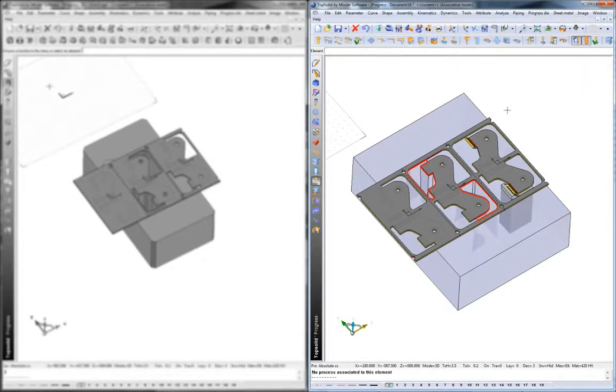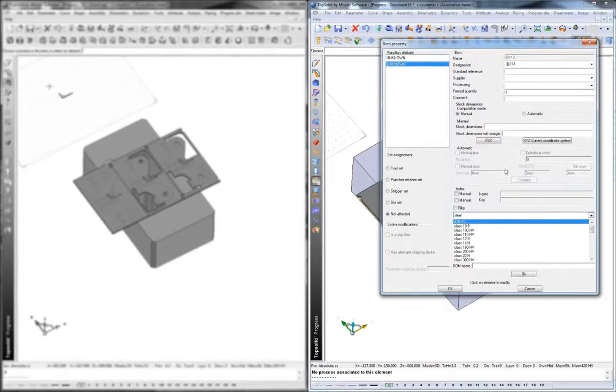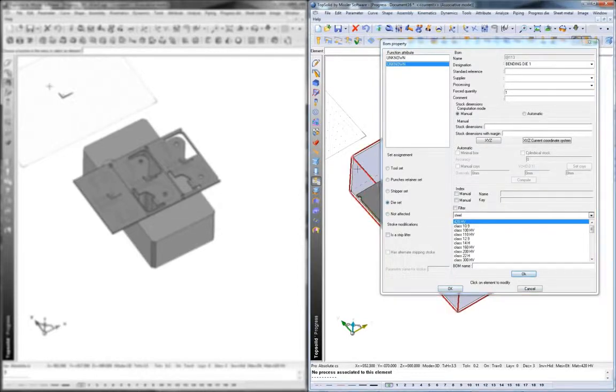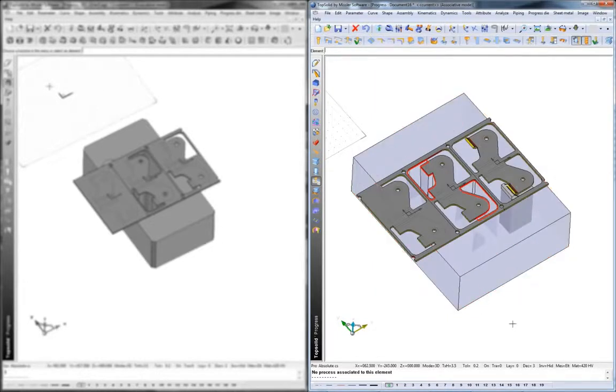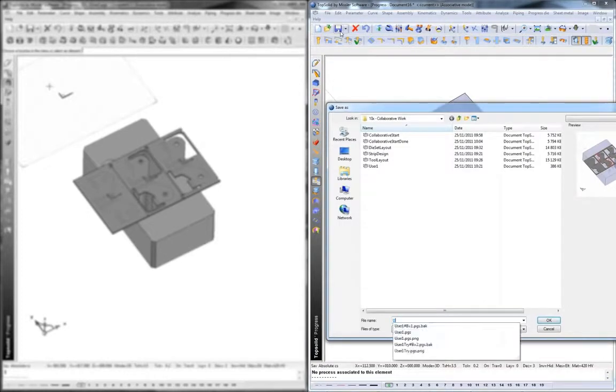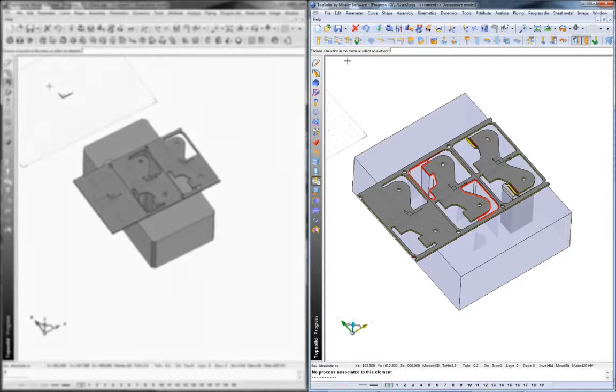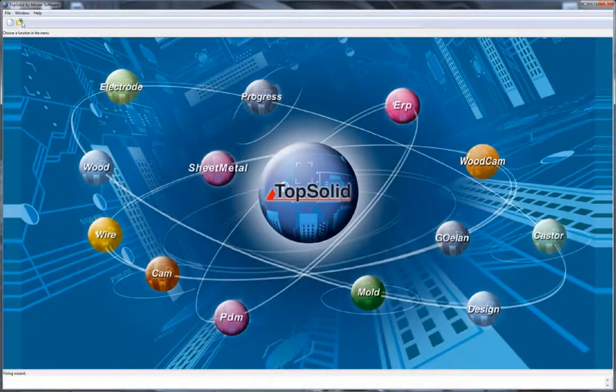And then from there, how about we set some specific bill of material properties? For example, we'll call this bending die 1. We'll put it in the die set. Beautiful. Let's grab that block and we'll also put that in the die set. Perfect. And we'll save. Like that, User 1's design and User 2's design are complete.